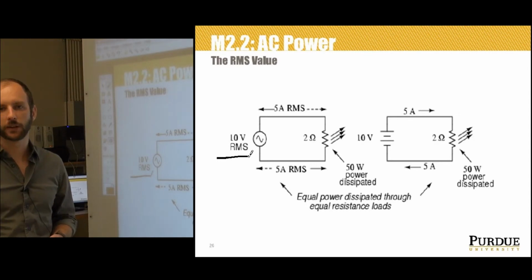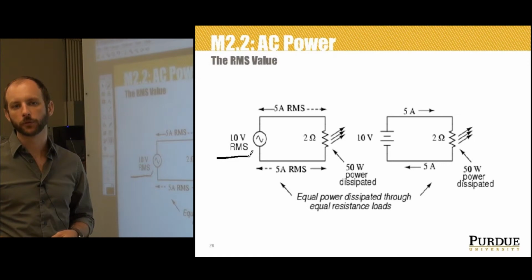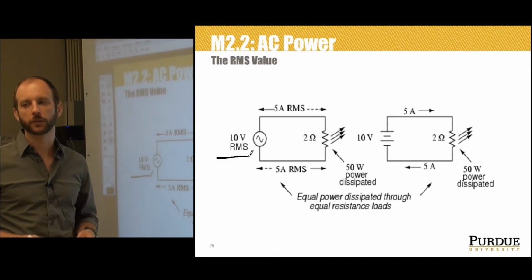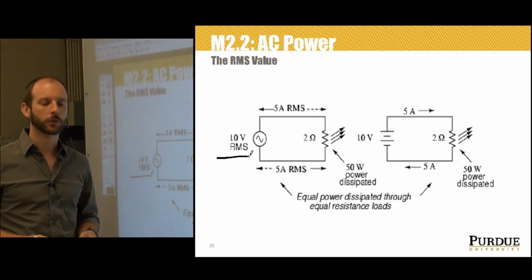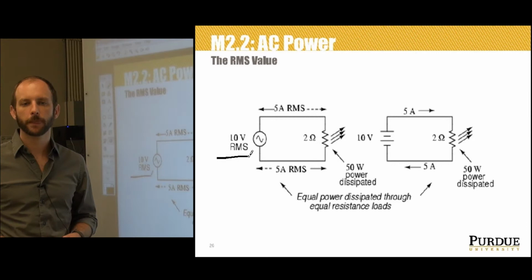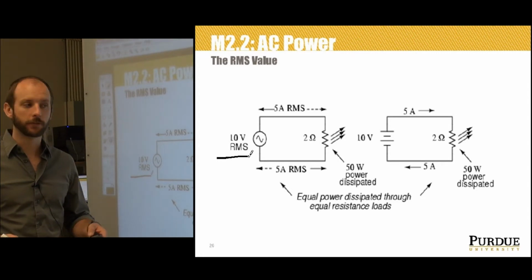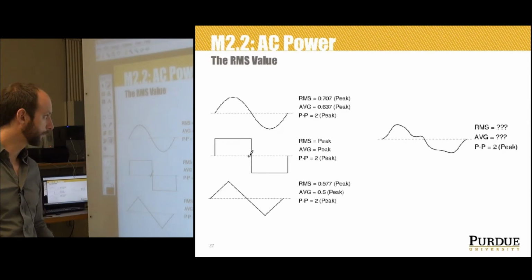However, when rating insulators for service in high voltage applications, peak voltage measurements are the most appropriate, because the principal concern here is insulator flashover caused by brief spikes of voltage, which is irrespective of time and particularly related to the peak value of the voltage.